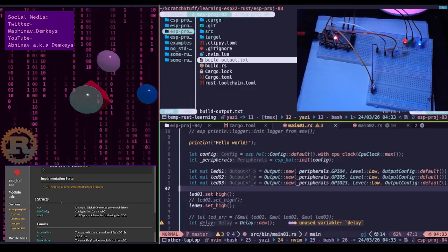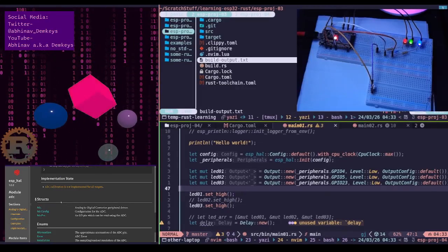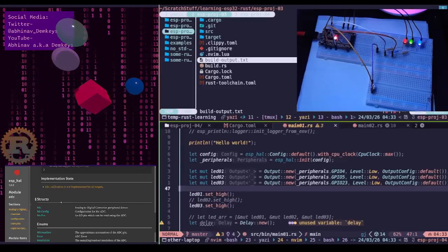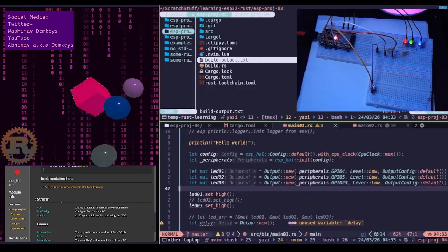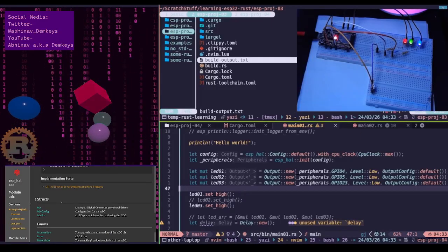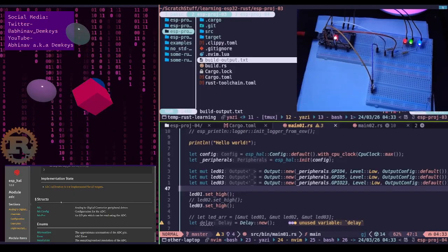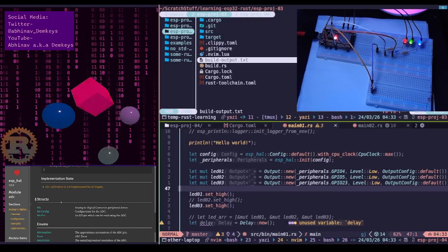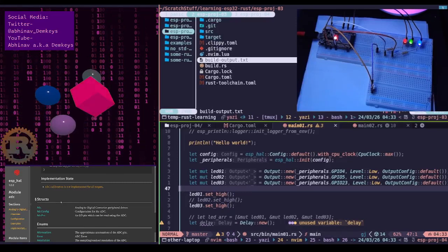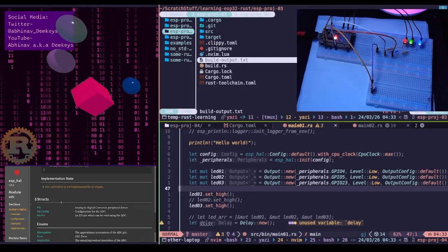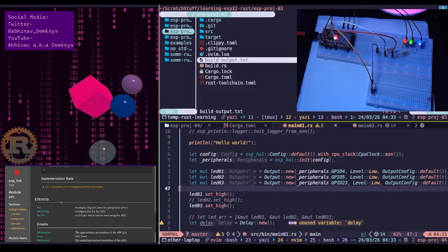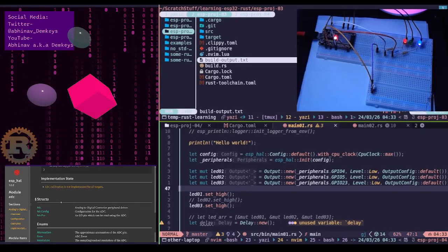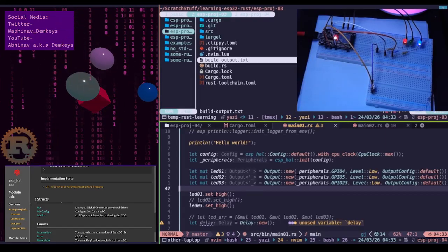Okay. The potentiometer as a sliding tap. A potentiometer is just those two resistors, but the middle point can move. Inside the pot, you have one long track of resistive material. The total resistance, let's say 10K ohms, never changes between pin 1 and 3. However, your wiper slides along that track. Your wiper is pin 2.